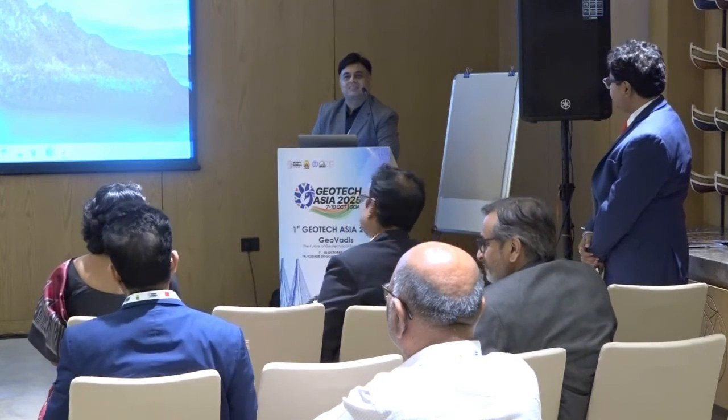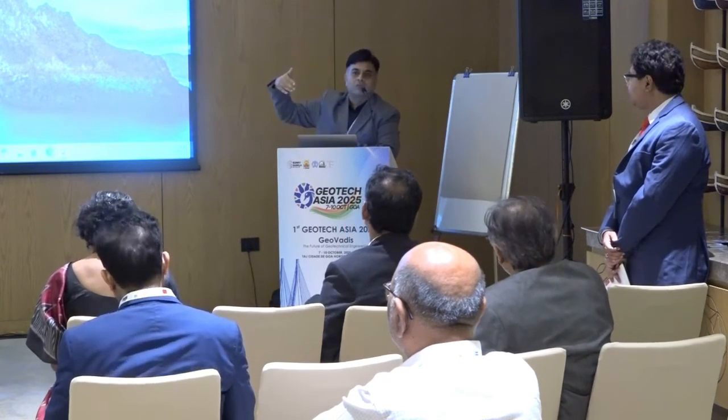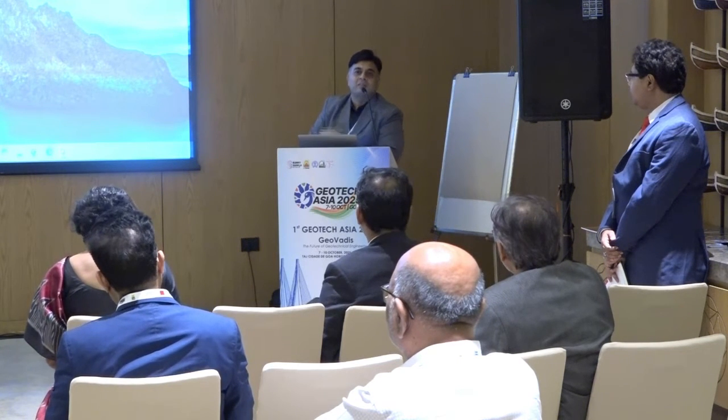Settlement marker. But again, then at least it will reflect the settlement of the down layers, not the top one. And that layer is already a bituminous layer or a relatively hard layer, which is not deforming with the ground. So you need to understand before putting it. That's what I can say, sir. Yeah. Thank you. Any other questions, sir?